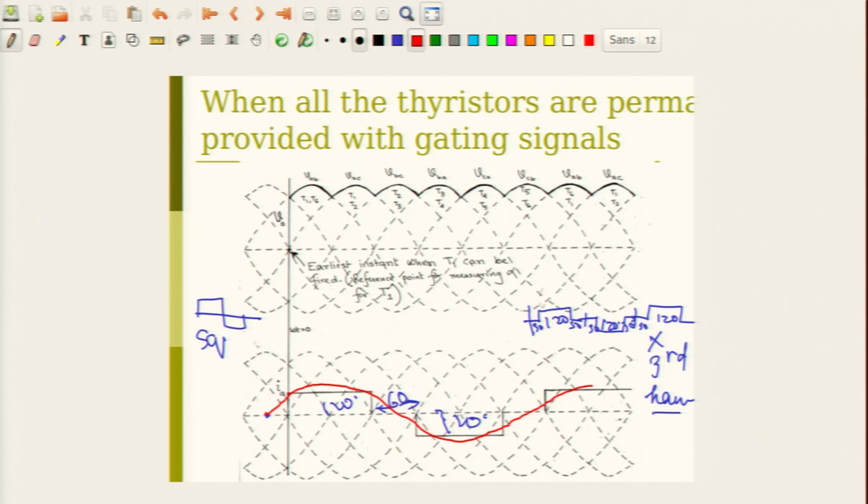Okay. So, I have not drawn it, it does not look like a nice sinusoid, but you get the idea, I hope. So, this is the waveform which you get, and if you look at this waveform here, this is 30 degrees, this. In fact, this voltage here is VAB, and you will find that in fact IA is in phase with VAN.